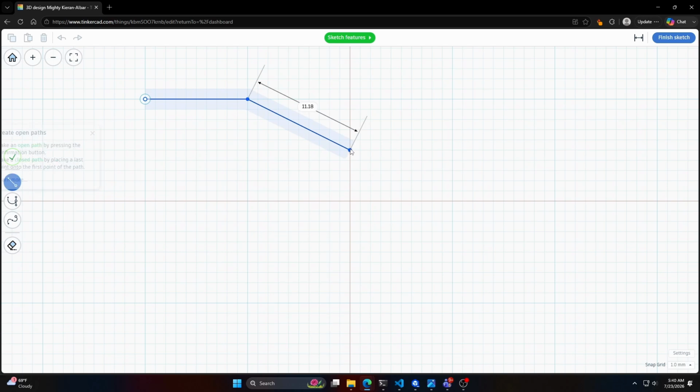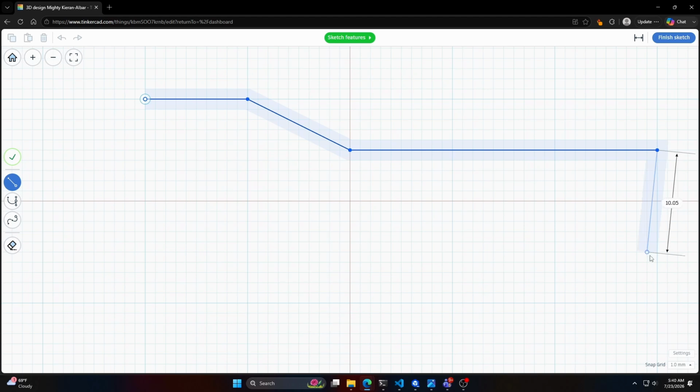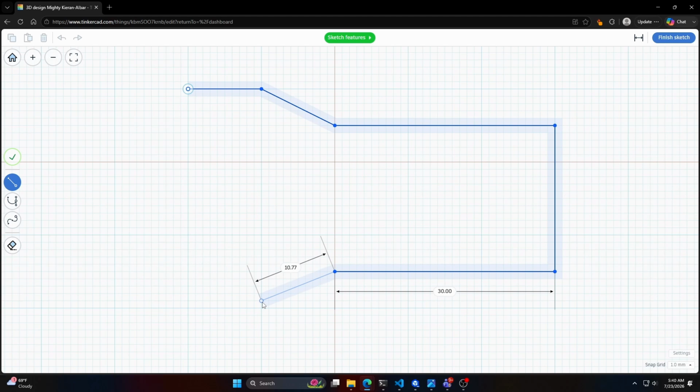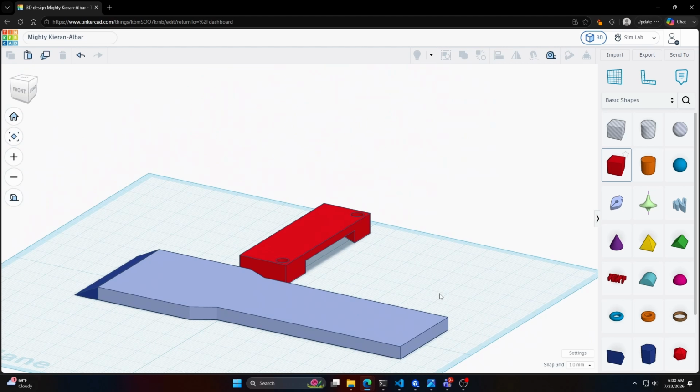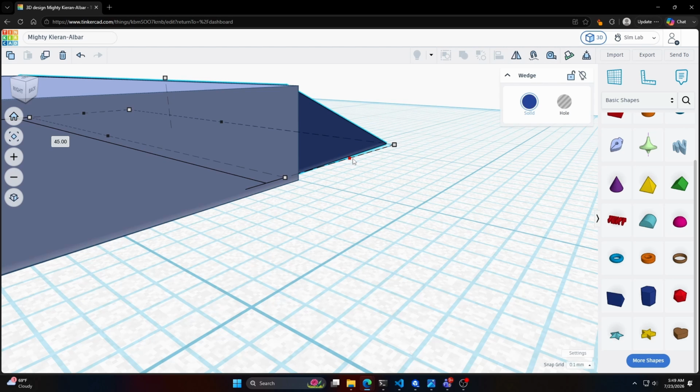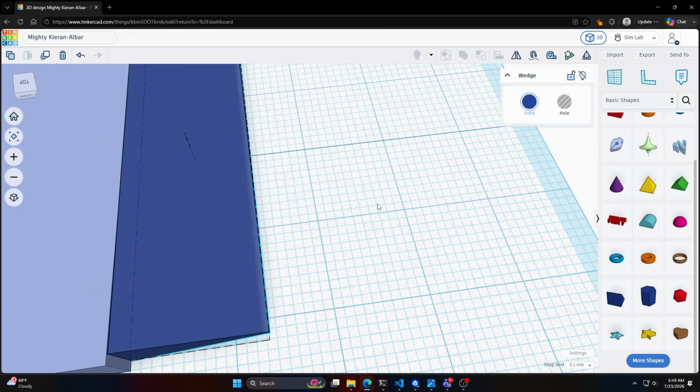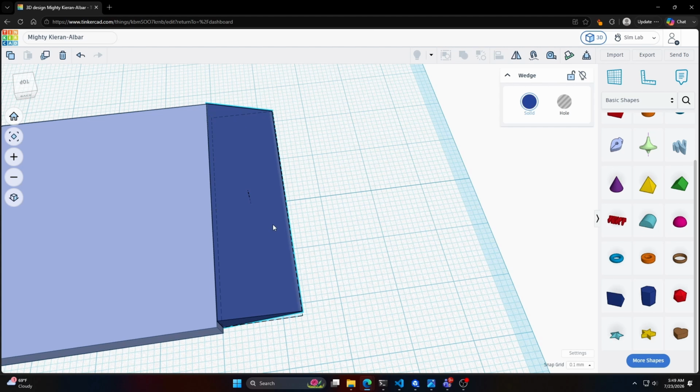Now, if you have never done 3D modeling before, Tinkercad just feels like magic. Without any tutorials whatsoever, I was able to design the scraper in about 20 minutes, which is fantastic. That said, it doesn't have true parametric modeling features. There was no sketch constraint engine. There was no history tree. Really, the precision work was just a bit clunky, where I couldn't get two pieces to line up just right, and I had to delete it and start over.